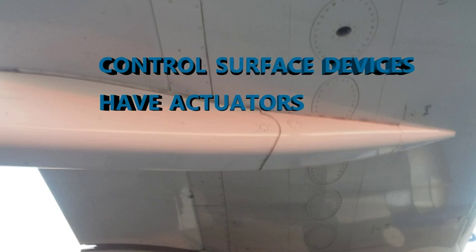And I'll get into later how they're connected to the computers, which computers are in charge of which actuators, etc. It's a whole network of connections. And for your elevators, you have 1 and 1. So for each elevator, you have 1 servo control type of actuator and 1 electrohydrostatic actuator. Okay.